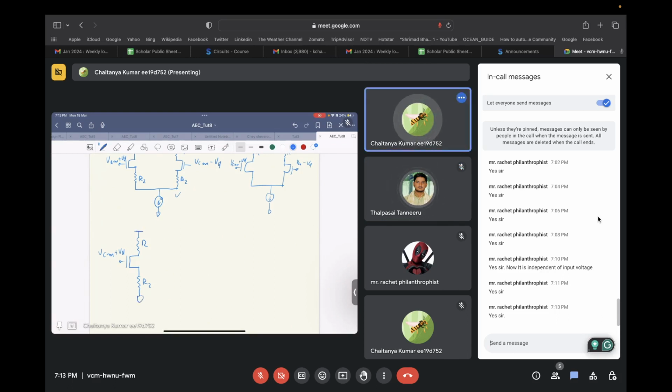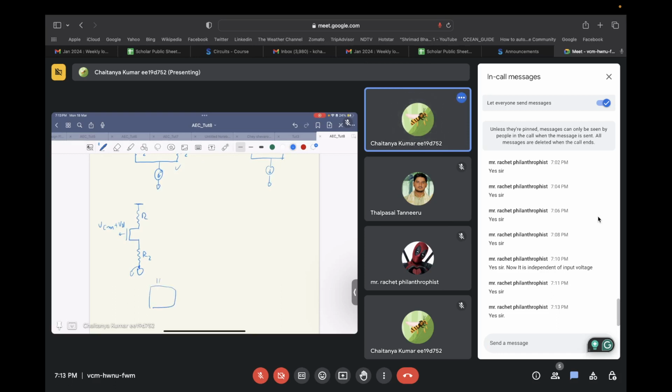Your circuit should look like this, correct? So you want a ground over here in the differential circuit. To achieve this ground, you have seen that if this is half circuit A and this is half circuit B, where one has VCM plus VD and the other has VCM minus VD, and you connect identical nodes of these two circuits, the differential midpoint will become an incremental ground.